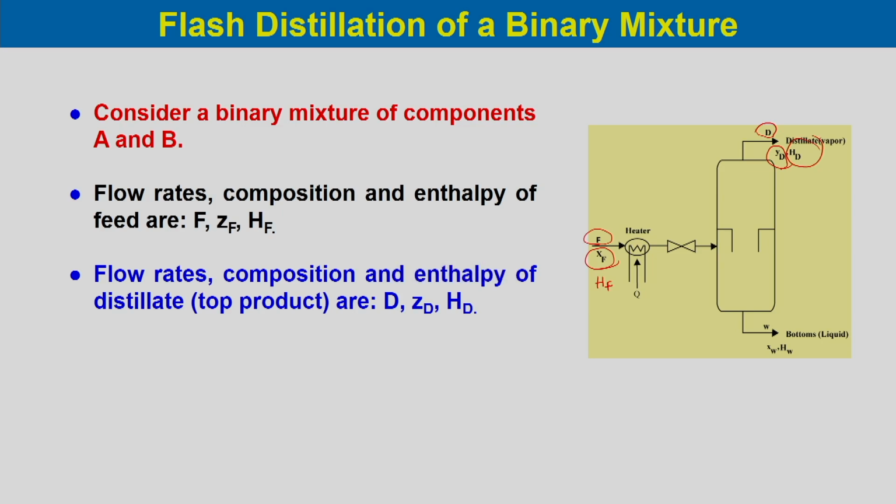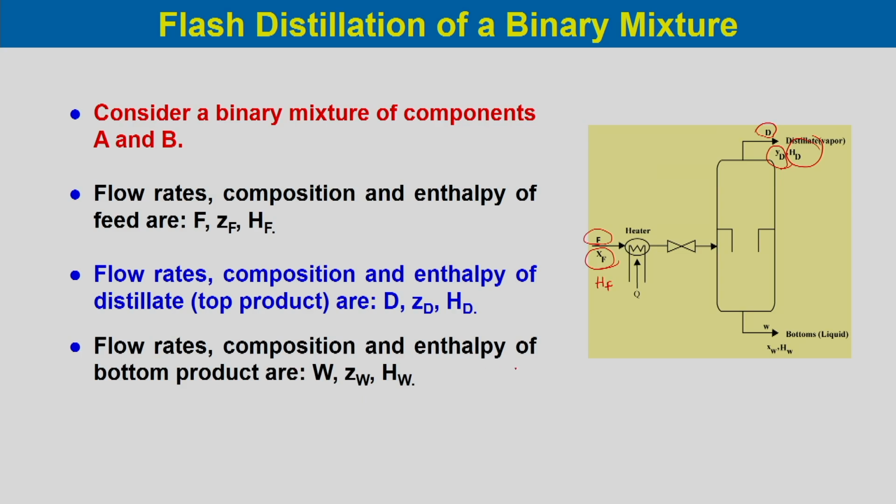Then we have the bottom products, with their flow rate, composition and enthalpy, as shown over here. W is the molar flow rate of the liquid which comes out as the bottom product. The composition of the solute, that is the lighter component, is XW, and its enthalpy is HW. So the conditions for a particular solute are given at the feed, distillate and bottoms.